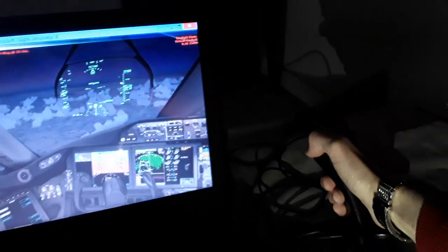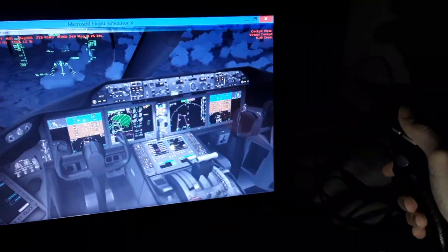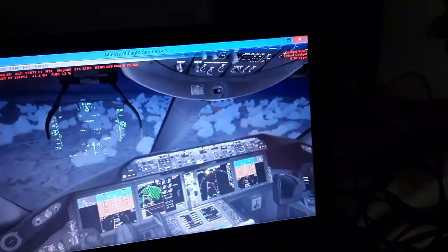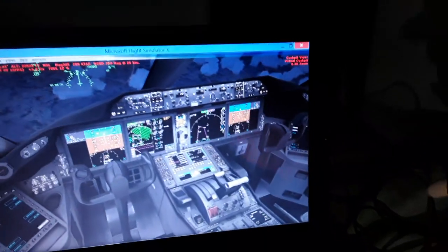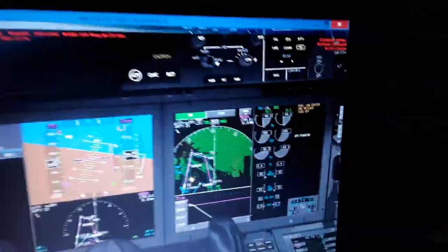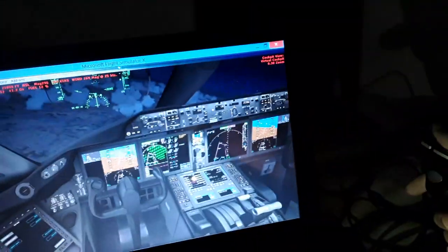So you see how beautiful views we have from the aircraft, and we have 7 more minutes for the flight to reach the airport, make a more steep descent. Use idle thrust for this. And we need to cross through some waypoints, as you can see, as we are descending.